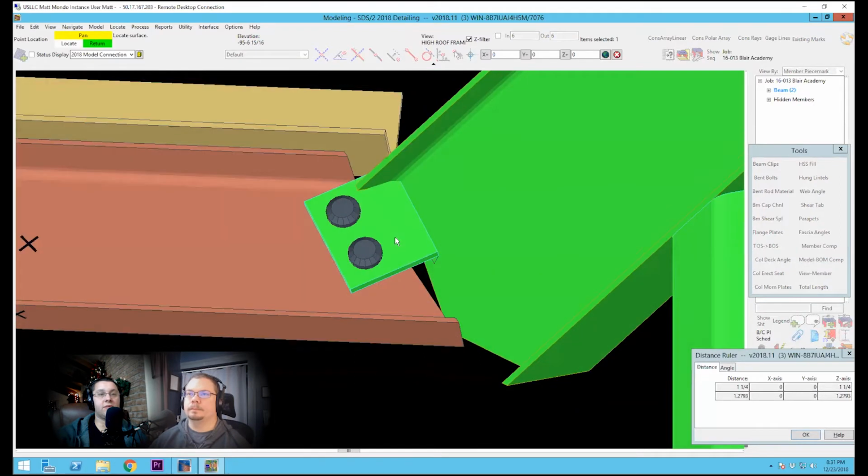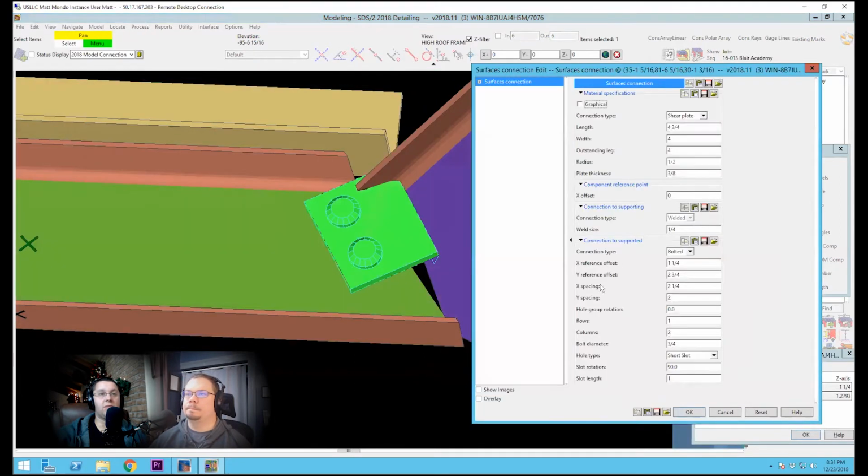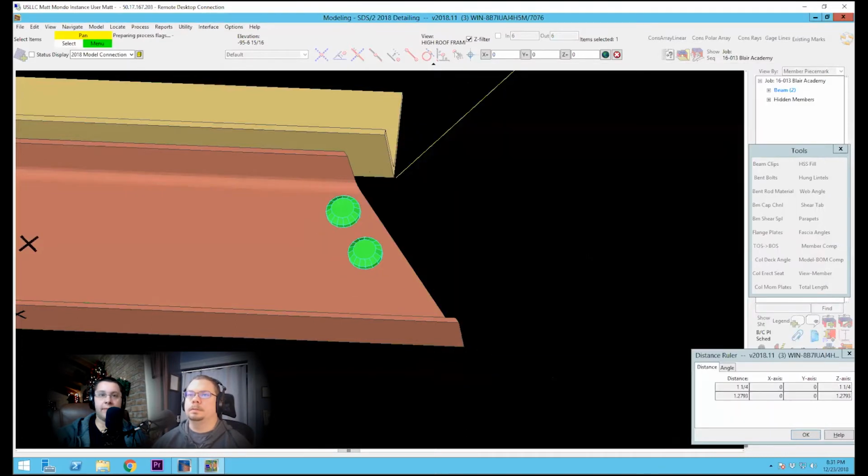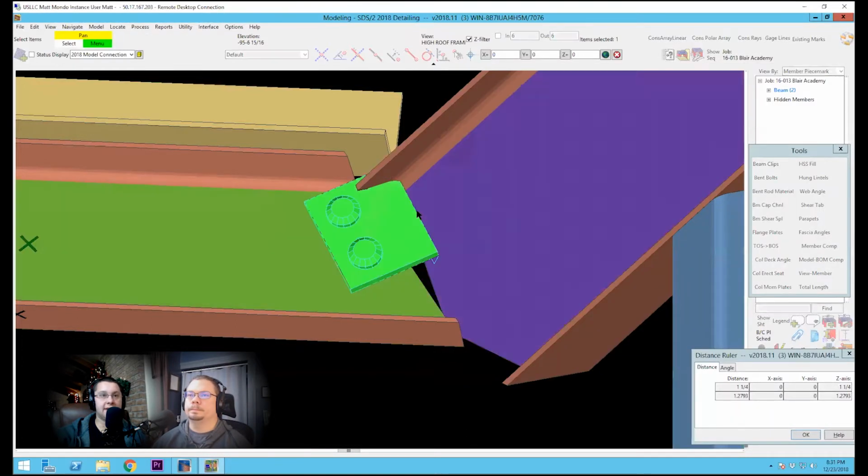But even that, right there, you got 90% of what you need. Now, if you just make a big old plate there, I could always do a cut layout if I want to do a custom hole pattern or something like that. Surface on the plate, and it's all good. It's fine. But to get that in the right plane where it sits on that web nice, major time saver. And as I like to say, minutes add up to hours, add up to dollars.